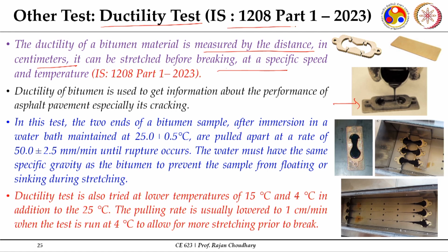Standard dimensions are given in IS 1208 part 1, and you stretch it in a water bath. Why? To maintain a standard temperature, it is kept in the water bath and stretched. Here both the ends are getting stretched, and you stretch it at a standard rate. It says 5 centimeter per minute.